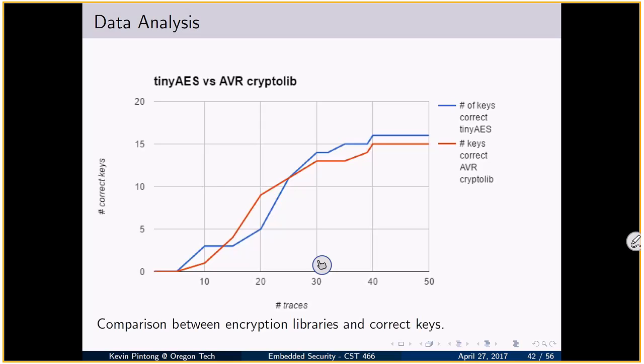They can be salted on an embedded system. Some people said that they can't be salted or can't be hashed on an embedded system. That is not true. It may take longer depending on the capabilities. The question was: thinking in terms of an embedded system, why are embedded systems more vulnerable to password attacks than a typical desktop? Some people said the password can't be salted or can't be hashed. It can be hashed. It can be salted. A lot of times it's not.